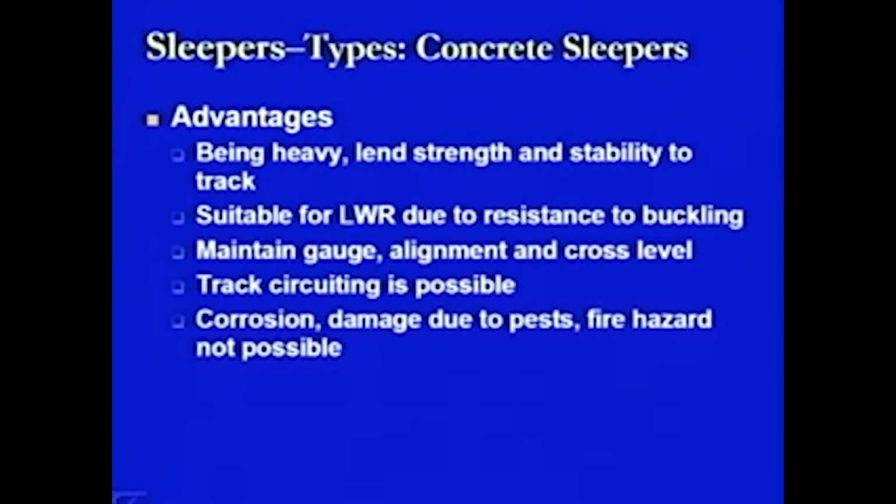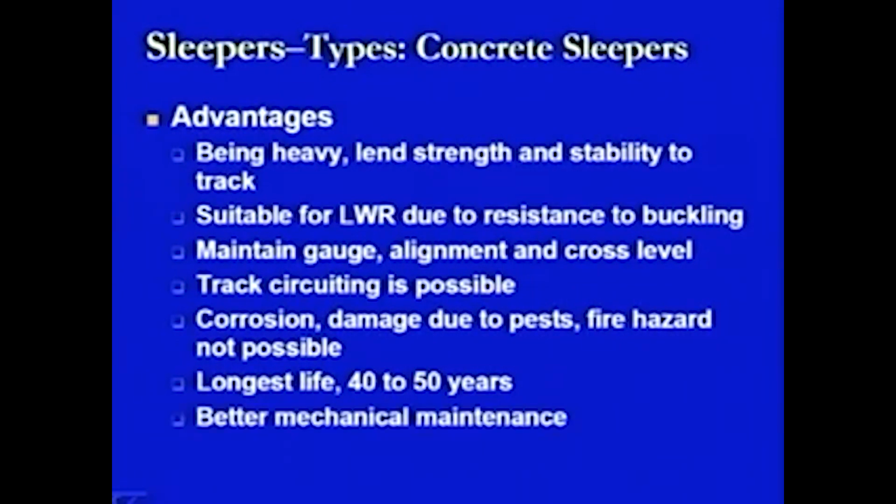The corrosion, the damage due to pests, or the fire hazards, all these three conditions are not there in the case of concrete sleepers. They are not going to be affected by the corrosive conditions, by the fire hazards and by the pests. They have the longest lifespan, even more than 50 years. Better mechanical maintenance is possible in the case of the concrete sleepers as compared to the previous sleepers, because of the easiness of the design of the concrete sleepers.